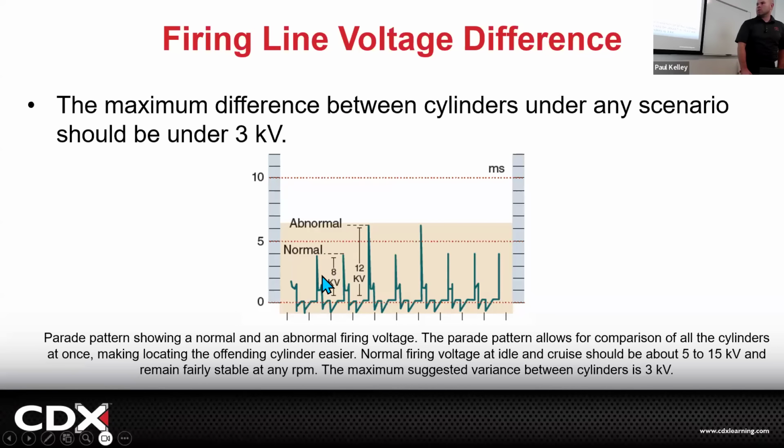But look at, let's say this is 1, this is 2, look at 3 and 5. What do they have? A really high firing line, or a really high spark line. So what do you think would cause really high? Brian, don't answer anymore. You got it. We got other people who didn't get it. Okay, why would it be really high? If really low meant low resistance, what does really high mean? High resistance, but why though?